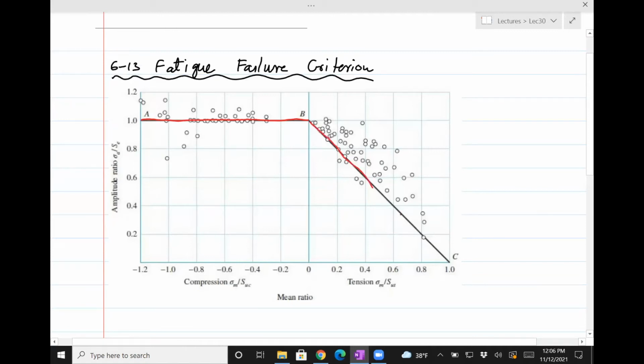Model we had, and that's the Goodman line, which we said is a predictor of failure. So the line says that all failures will be on that line, but you can see that some points are above the line, which is okay because this part is the infinite life, my bad. Infinite life. And this part is the finite life.